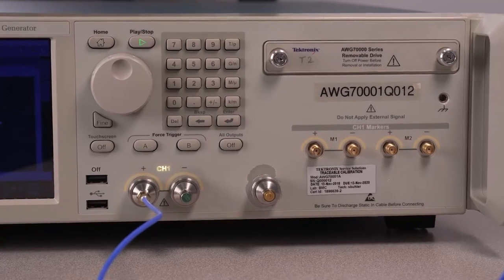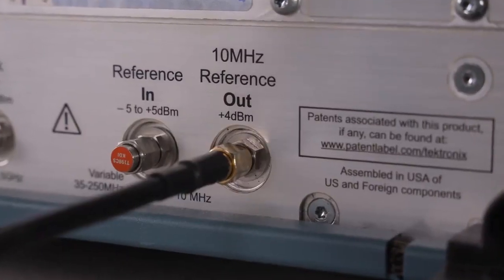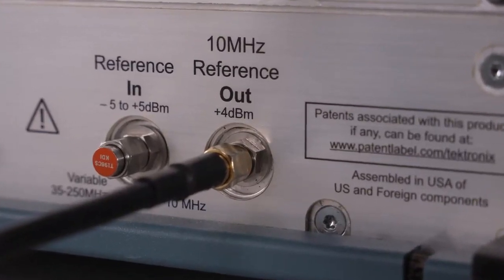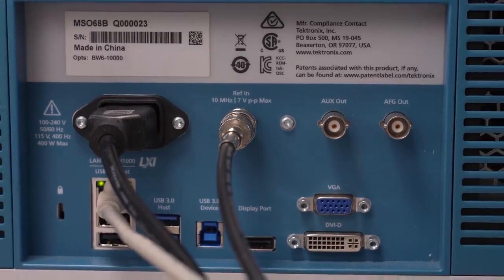The waveform travels out of the AWG to the DUT, where it's amplified by roughly 16 to 17 dB and then acquired by the 6 Series MSO B, where it is digitized and down converted into IQ data before being processed by the SignalView application. The generator and the oscilloscope also share a 10 MHz reference connection through their back panels.